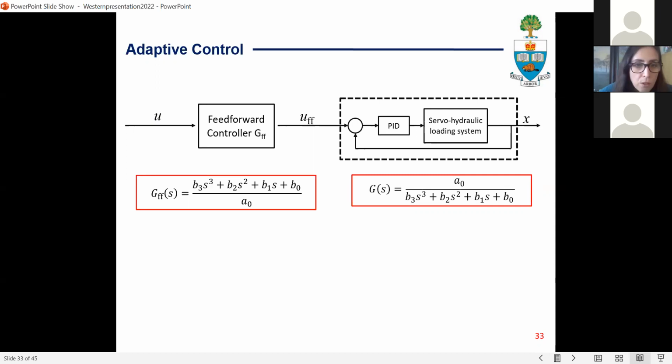So in theory, this looks very promising, but in the implementation there are challenges. In the sense that you have to do a very accurate system identification to be able to get a transfer function that defines this dynamics, and then you need to invert it, and in some cases there are even problems in this inversion. But if you have a nonlinear component, depending on the input, each time you do the system identification, you may have a system with slightly different parameters and things like that.